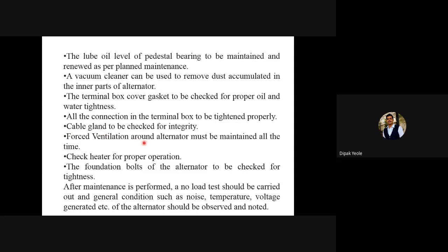Forced ventilation around the alternator must be maintained all the time. Check the heater for proper operation. Sometimes, depending on the plant where the alternator is, say a thermal power plant, we need heaters or a steam supply. So that heater or that steam arrangement we have to check.